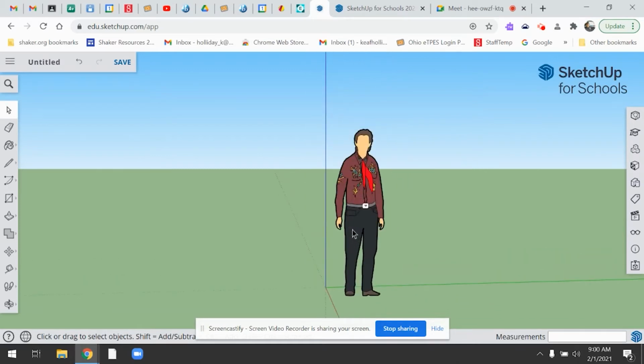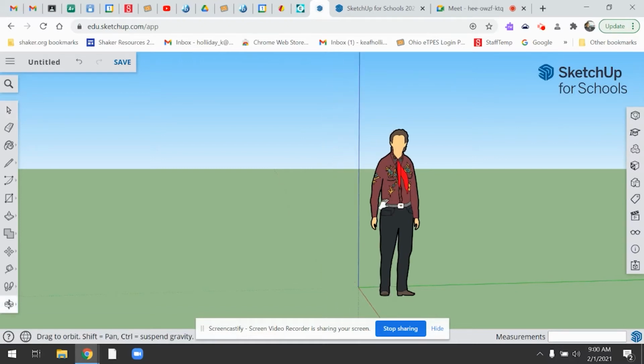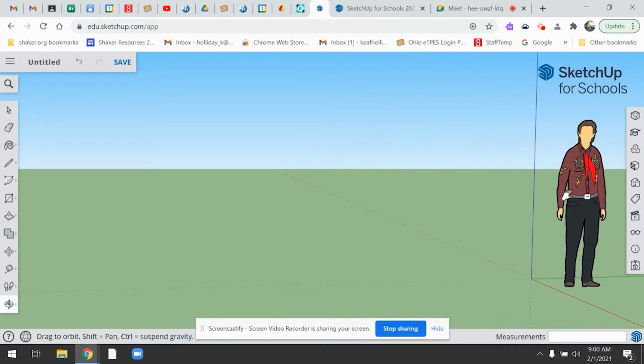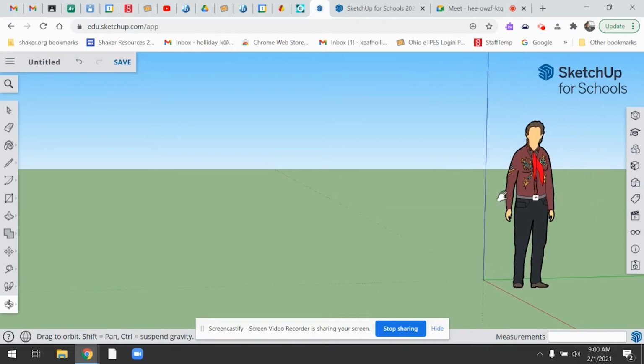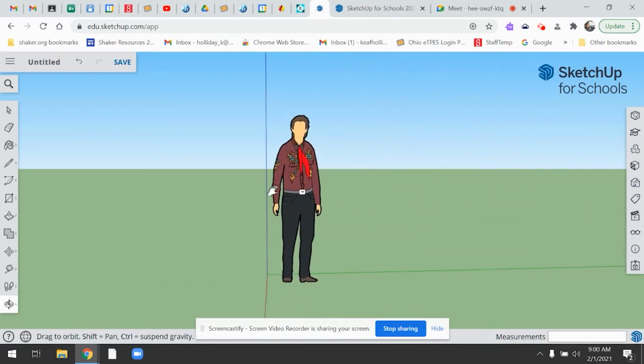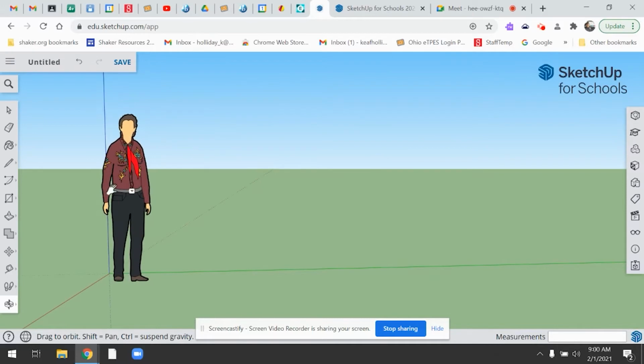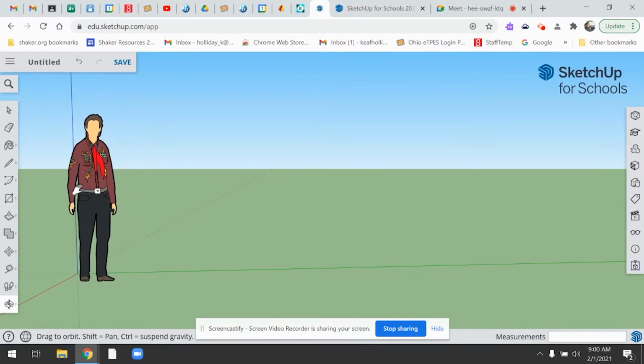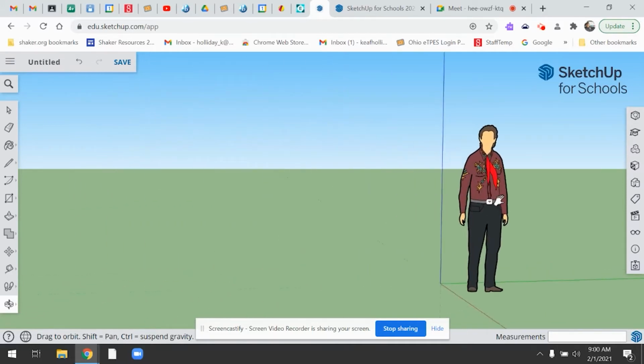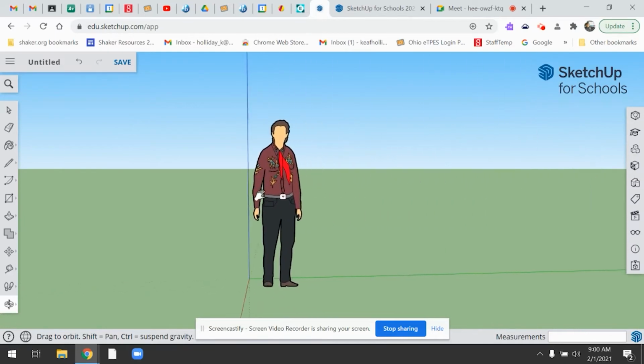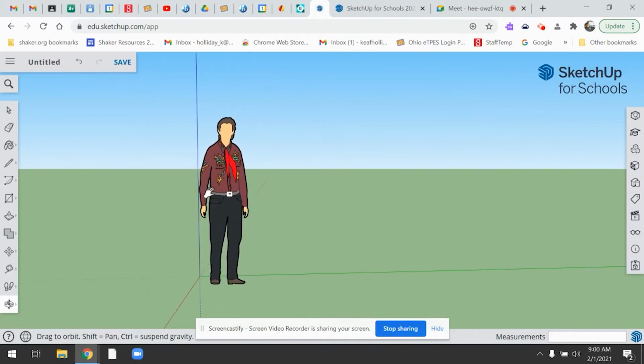These are very important tools with the mouse. Now, another tool with the mouse is to hold down Shift and hold down the middle mouse button, and you can literally pan to the left, press and move your wrist, pressing down with the middle mouse button, and move to the right, to the left. So you can move from left to right and from right to left. I'm holding down Shift to do this.